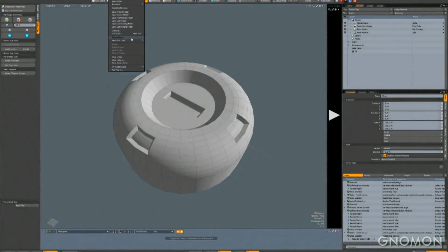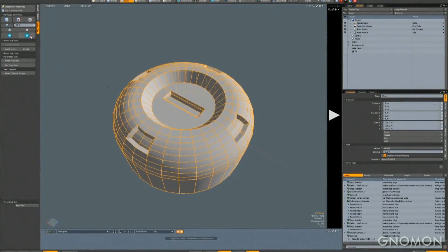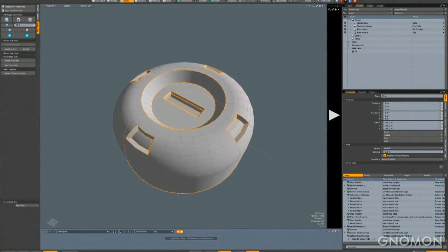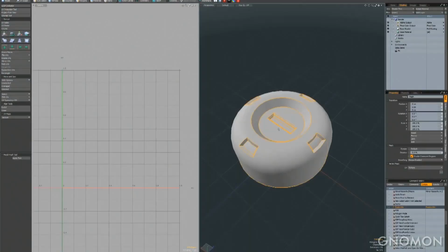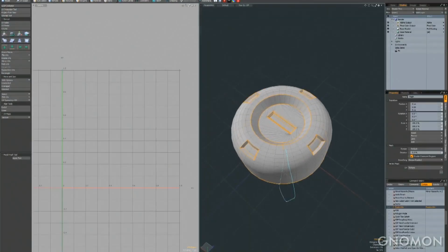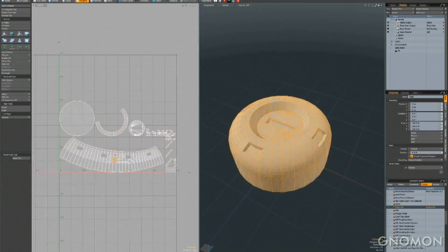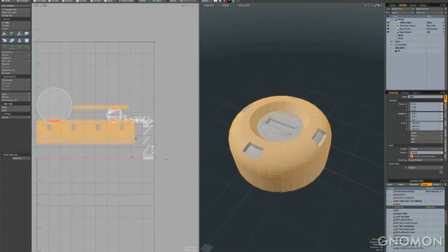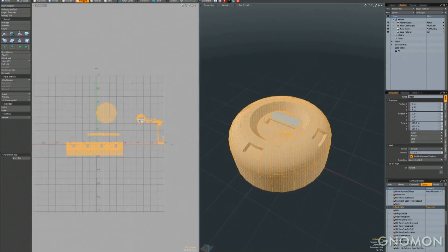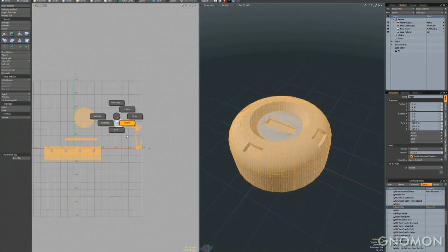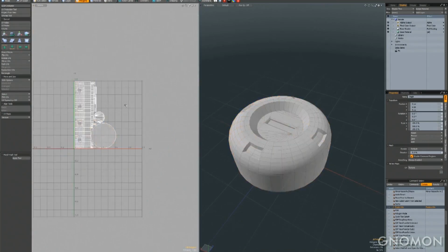Macros are another huge thing that I've been using more and more lately at work. Basically, just like a Photoshop action, you can start recording, perform a bunch of different actions, and save that out as a macro. This really empowers anyone and everyone to make their own scripts and speed up their own workflow in a bunch of different ways. Right here I made one that will automatically, without even doing a single click, select all the hard edges on a geometry and bring me right into the UV window where I can start laying that stuff out. And that's all there is to it.